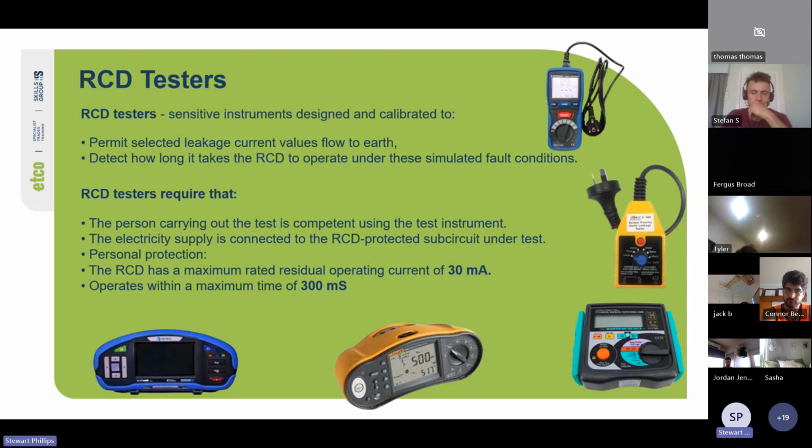32 milliamps. So if it's a 30 milliamp and it's tripping at 32 milliamps, what do you think is the lowest value it should trip at? So if you were to test the RCD and it's below 30, how low before you start thinking maybe you should swap it out? Because an RCD can be too sensitive as well.